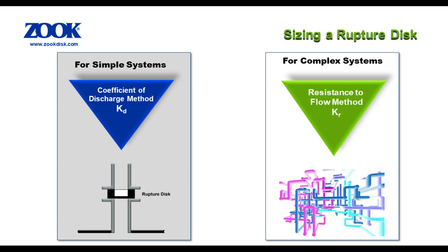Undersizing will allow the pressure to rise to an unsafe level because the pressure is being generated more quickly than it can be vented. Oversizing is equally dangerous because the device may not open as intended, limiting the device's relieving capacity. This is particularly true with reverse acting disks that require minimum amounts of burst energy to open the disk as designed. There are two recognized sizing methods.